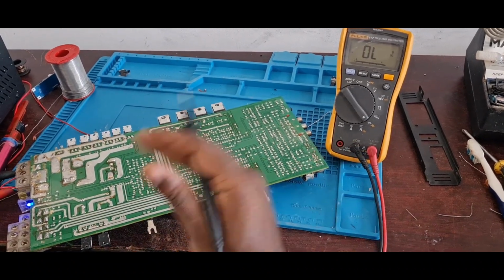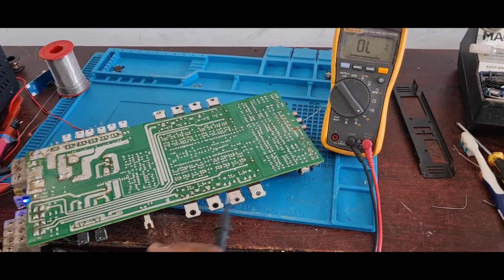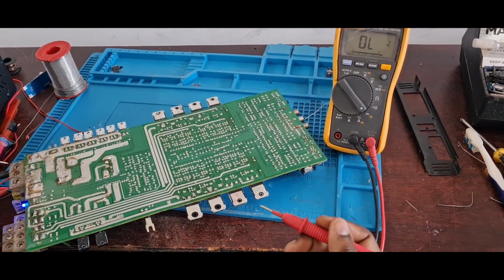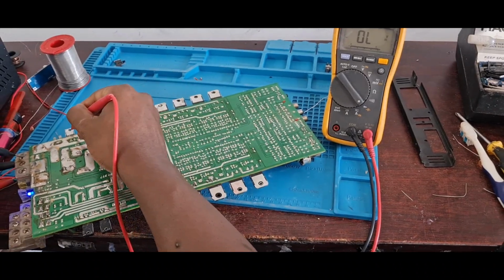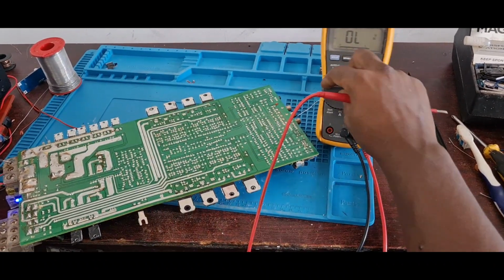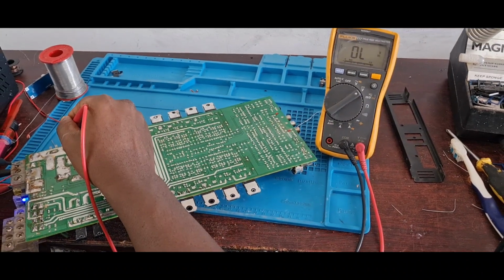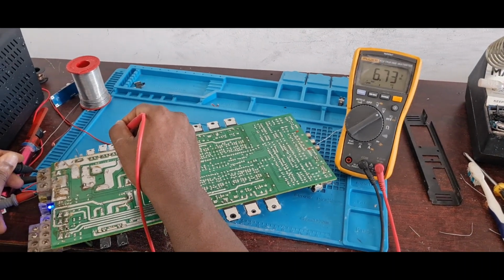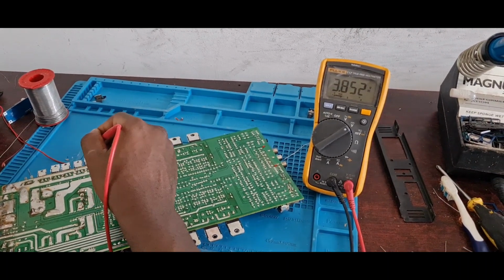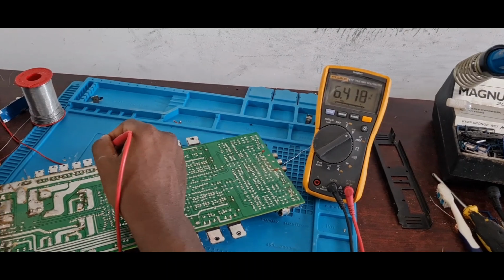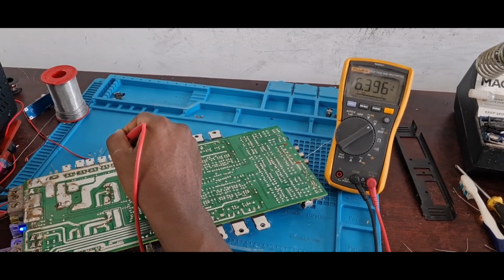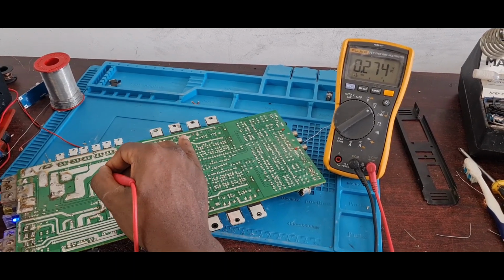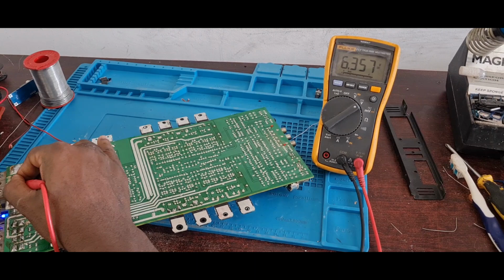So friends, I just took out the board to make the video a little bit shorter. I see the power light is on. I'm going to check the voltages the same way, ground my probe, and go to the power MOSFET on the drain. Sorry, I just put my multimeter to DC voltage. I'm getting 7, I'm getting 6. So something is telling me input voltages are not right.